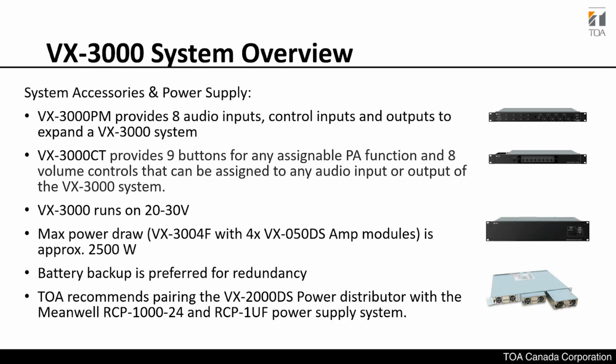There's breakers inside it, so in case there's a surge, it's protected, and in case one amplifier module shorts out, the rest are not affected. Only that module is isolated, and the problem is also localized to that particular module. And again, if you program it for failure monitoring, you can then flag that and send the notification to whoever the text is at on-site or your system manager.